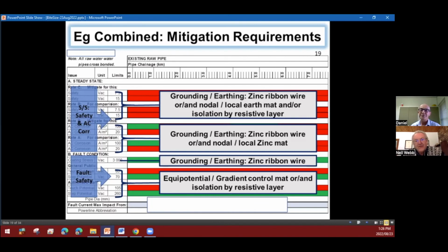Well, one way we can do it is to say, well, I don't care, and I go off, I've done my thing. But we're not that nasty, and we do know that CP impresses current on the pipe, which is coated, and the result of the excellent coating is that we've got such a low current demand from the CP. Now, when we ground the pipe with a bare conductor, we're increasing the bare part of the pipe, and the CP has to put on a lot more current to still maintain that negative potential on the pipe. The CP system would not be able to do this.